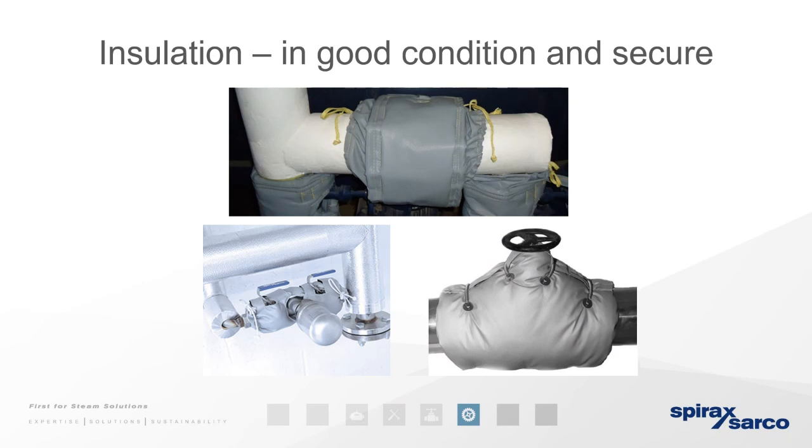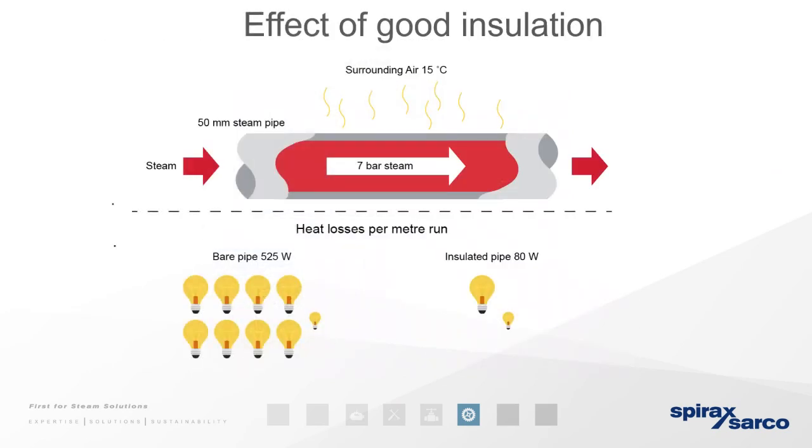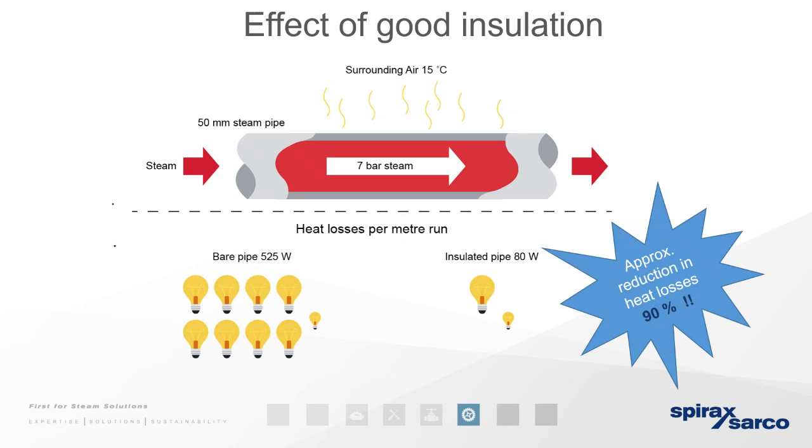But not just that. When you have a look at uninsulated pipes, these are generally the cancer of a steam system because of the heat emissions that you will see within it. So you cannot see the loss, but you get the condensation through the heat emissions, and therefore you will create so much more water within a steam system. But also, if we are moving hot steam in a much cooler steam pipe, then we are inevitably going to see much more steam losses as it gives heat to the pipe and produces condensate, which means not only distribution inefficiency, but also more steam traps required and a greater risk of erosion, corrosion, and water hammer. And there we can see if you have a proper insulation system, we can reduce those heat losses by up to 90% of it.